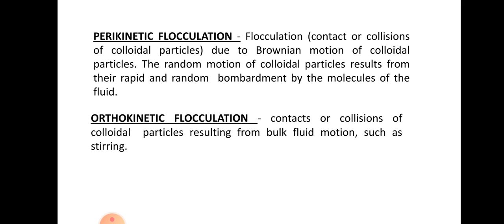Orthokinetic flocculation means the contacts or collisions of the colloidal particles resulting from a bulk fluid motion, such as stirring. When you stir, there will be collision of the colloidal particles, and thus it forms flocks. This is what happens in orthokinetic flocculation.